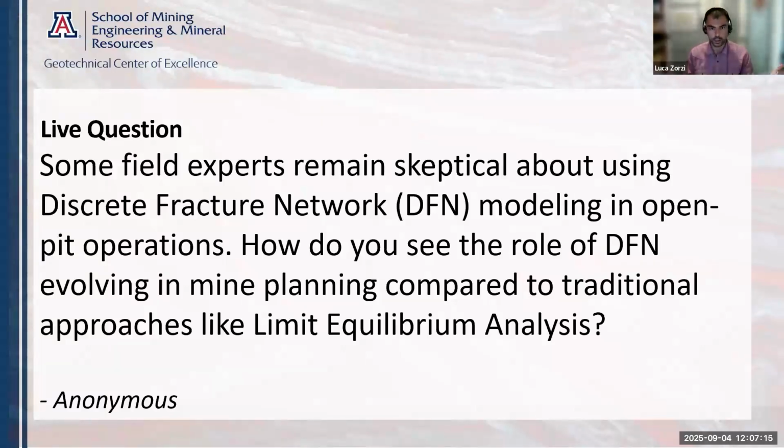So do the mapping, do the scan lines, which is the other thing that we tend not to do that often. Do a lot of scan lines, do a lot of window mapping, get your continuities on your larger scale structure and your small scale structure. And then consider using DFN, because then you create a little bit more realism, or at least you can test scenarios to understand the most probable conditions in terms of structural setting, like joint systems, that your slope has, and you can plan or run analysis accordingly. So I am a big advocate of DFN just because it brings more realism to your analysis.